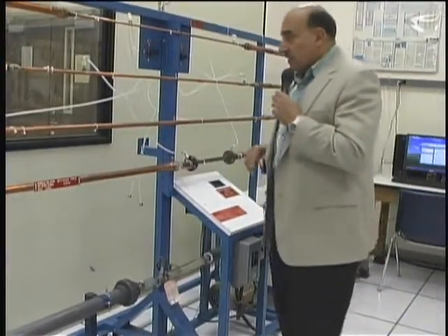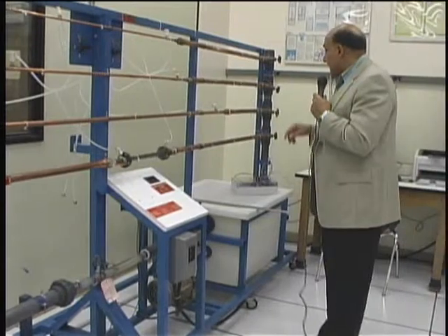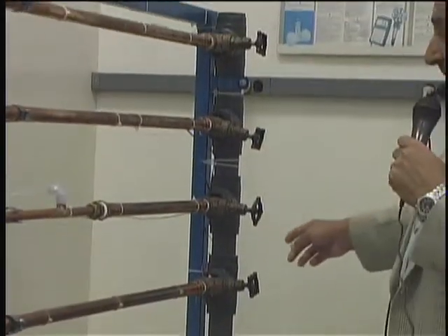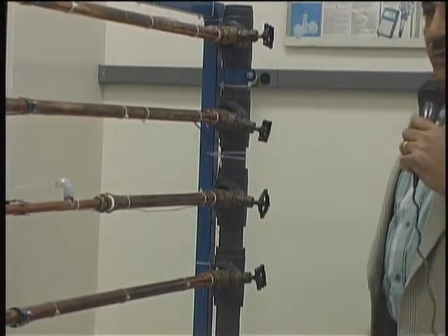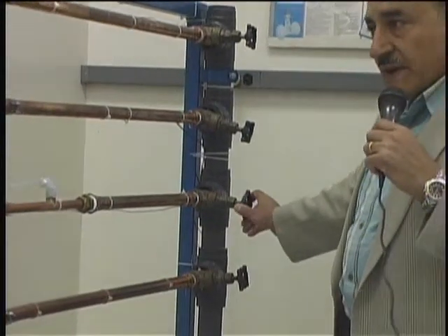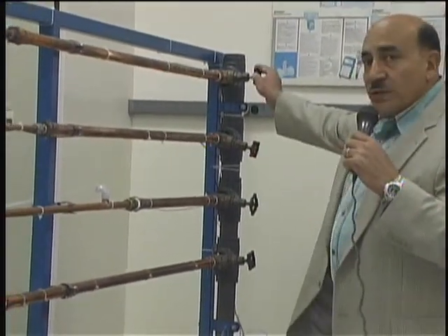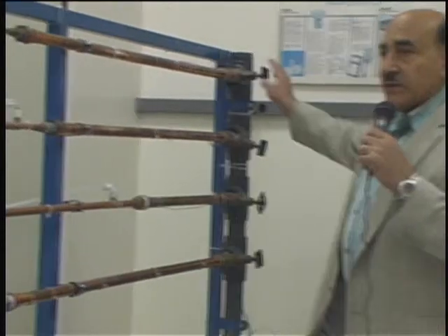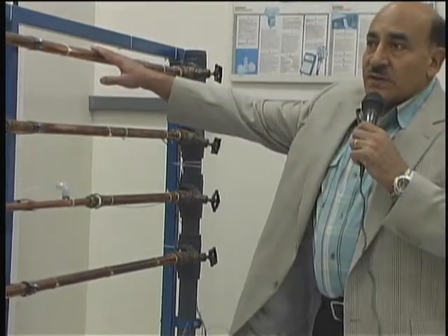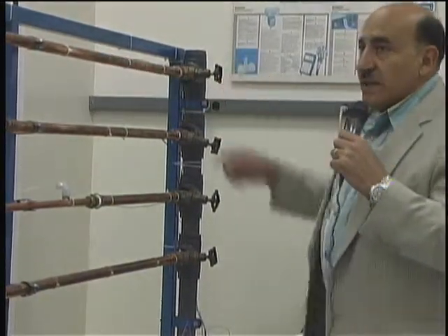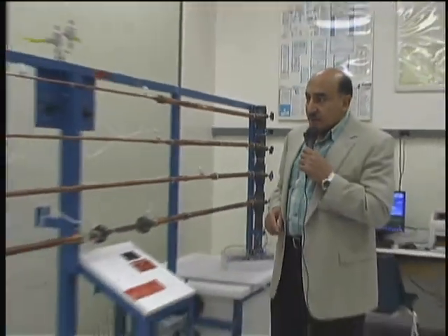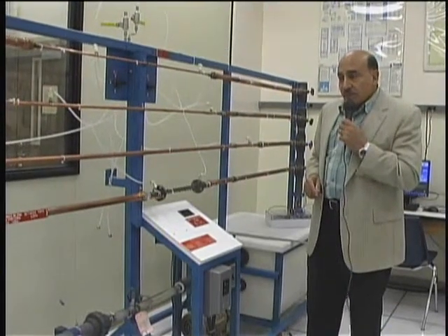So for example, if you look on that end of the test stand, you'll see that we have 4 valves, and the 4 valves control the flow portion that goes into each one of them. If you shut off, for example, these 3 valves, this one, and this one, and this one, and you open the top one, then you have already determined that no flow goes into the bottom 3, and the full flow will go to the top one. And if you open it completely, that will give you 100% of the flow rate that is attained with the centrifugal pump.